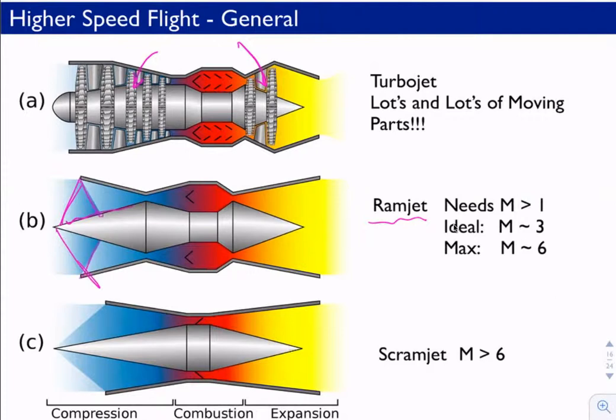And so the fluid, as it passes through here and necessarily turns around this, forms this oblique shock, an axisymmetric oblique shock, and a compression occurs. Now, in the case of relatively lower Mach number but supersonic flight, somewhere around Mach 1 to 3, you can slow the flow down enough so that you have a throat here.